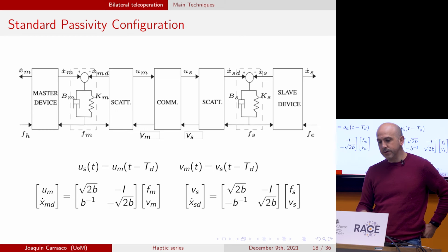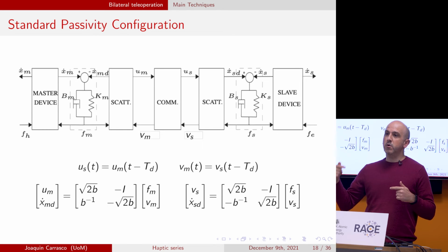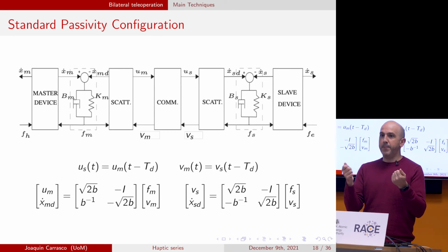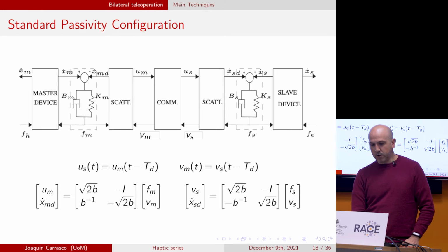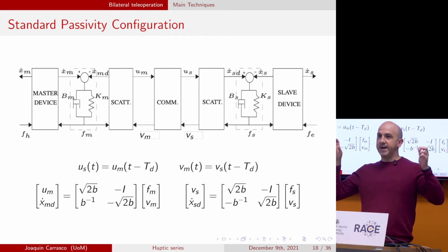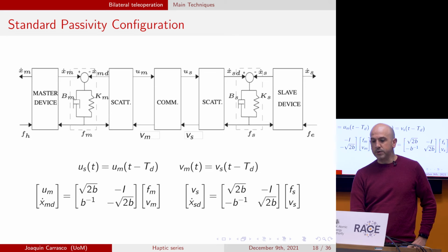Finally, once we know where we want the robot to be, what we are going to do is put in a spring damper between the position that we want the robot to be and the position where the robot is. The robot is in this position. For a nice control system, it has to be in this position here.